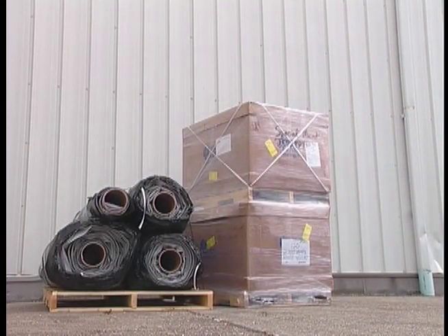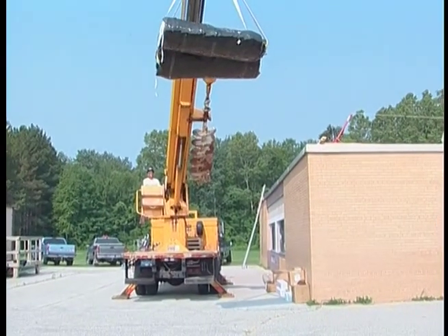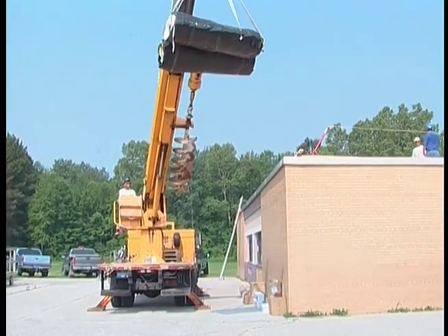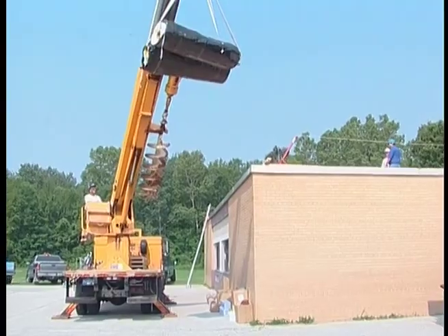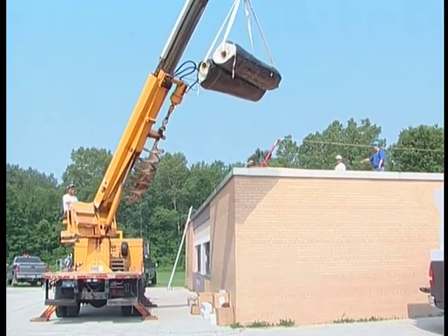Never store any material on or near ponding water or where water may run off from higher elevations onto your materials. Elevate off the roof all accessories that are packaged in cardboard boxes and cover them with tarps securely and completely to keep them dry. You must have adequate personnel and equipment to safely lift and place the Duro-Last roofing system onto the rooftop. You will have determined the necessary equipment during your initial site survey.